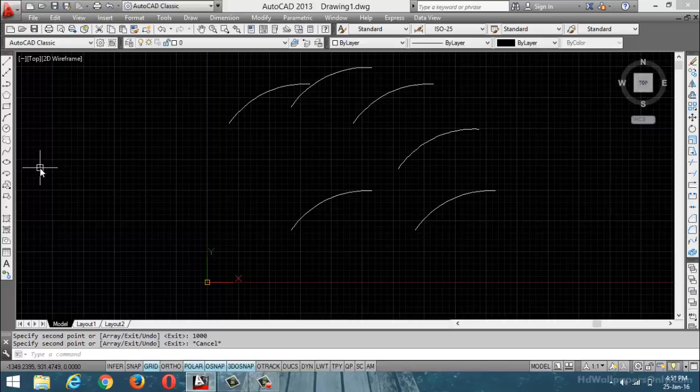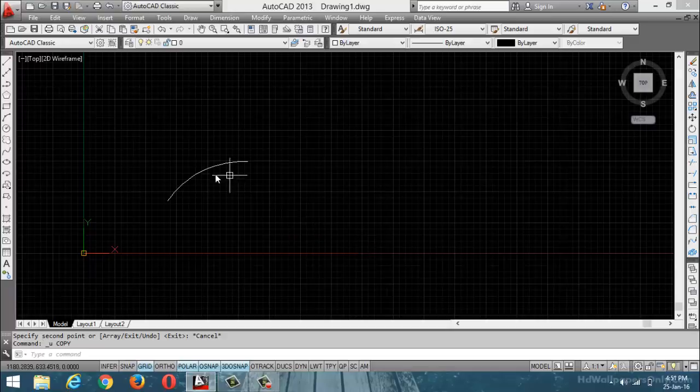Again, one more requirement. Now I am going to create 20 copies of this object in zero angle direction. How to create that one? Directly you can select 20 copies of this one in zero angle direction. Same thing: copy, select object, and set the mode as multiple. Specify the direction 0 degrees, then specify 2000. Next, second item 2000 plus 2000, 4000. Next 6000. That is a long operation.